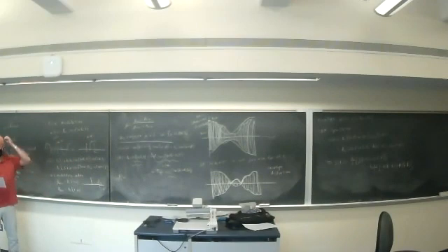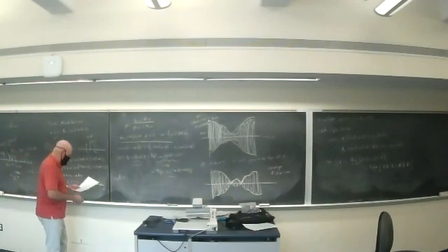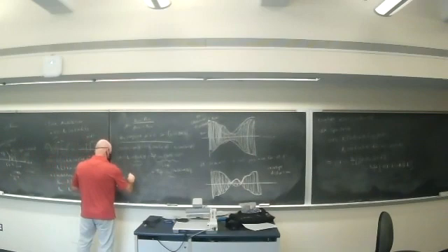I know it's been a while since you had circuits too. Divide by square root of 2, right? So if it's 10 cosine, the RMS would be 10 divided by square root of 2. Square that, it's 10 squared over 2, right? So the power is actually AC squared over 2 due to this term.